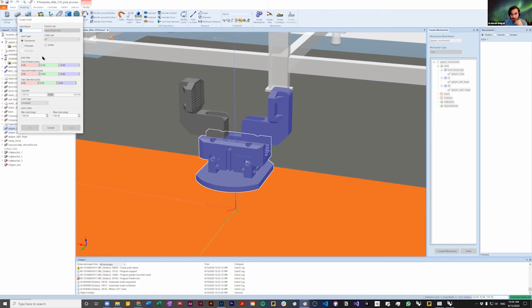So basically, if you wanted to define this gripper, we want to somehow say that, okay, this part of this tool goes this way and this way, and this finger at the very same time goes left and right. So it is called a prismatic motion. And we can say that the left finger of this tool slides back and forth, and I know that the amount that it moves is only 20 millimeters. So if it starts from 0, it can move for 20 millimeters.